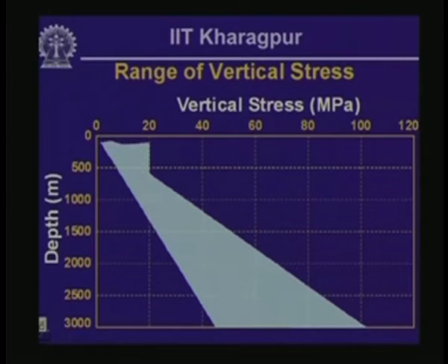So that will give you an approximate estimate of the vertical stress within a mass of rock at some depth below the surface. This estimate is not going to work that well very near the surface, but if you go down to relatively greater depths like 500 to 1000 meters, then this particular method is going to work quite reasonably.